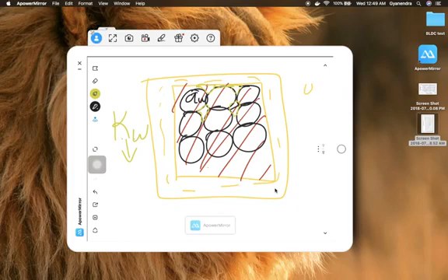Generally, for a single winding inductor, for initial designing you can choose 0.6 to be on the safe side, so that the windings will for sure fit into the window area. People have gone to more than 0.9, around 0.95 also, but those are professionals.